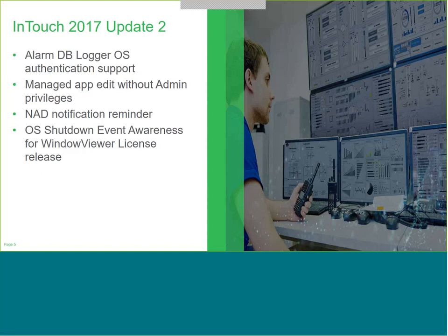They've also introduced a NAD notification reminder. NAD is Network Application Development, so it's pushing out applications across your network from a standalone InTouch app, very similar to the IDE where you manage it all centrally. You can still do that with standalone InTouch, but what they've now done is added a notification reminder. So if you have made a change to your application and you start to close it, it will say, do you want to notify those NAD clients and push this update out to all those runtime clients? You get that option there.